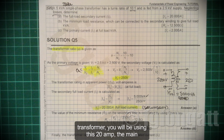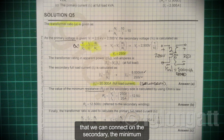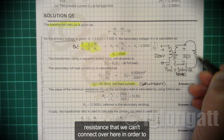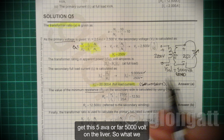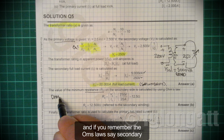Next question is quite exciting and also very useful, because we are asking for the minimum resistance that we can connect on the secondary in order to get these 5 kVA, or 5,000 volt amps, delivered. So what we need to do is use the basic Ohm's law. If you remember, Ohm's law says secondary voltage is secondary impedance multiplied by the secondary current.